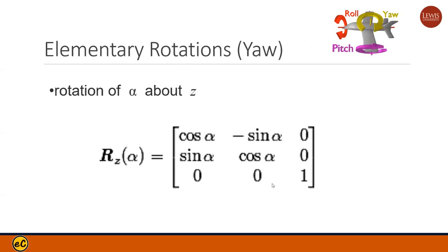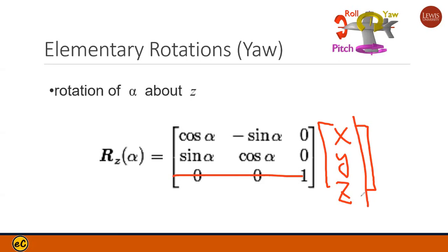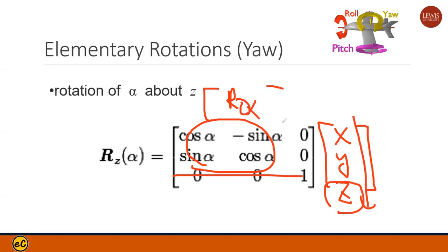A two-dimensional rotation based on the XYZ. So basically right here, let's look at this one. Your Z actually has no change. So you do have XYZ if you have original data here. So in the last line, your Z is no change. You take the same Z, right? Your XY would actually work on this two-dimensional rotational matrix with alpha angle. So alpha angle is your yaw.